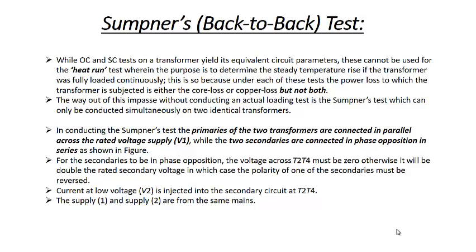But we did not conduct them simultaneously. We conducted them separately. But in usual practice, when the transformer is used, the two losses are occurring in the transformer simultaneously. In the open circuit test, we have only the core loss present, and in the short circuit test, we have only the copper loss. So the heating will be less in both the tests. What I mean to say is that.